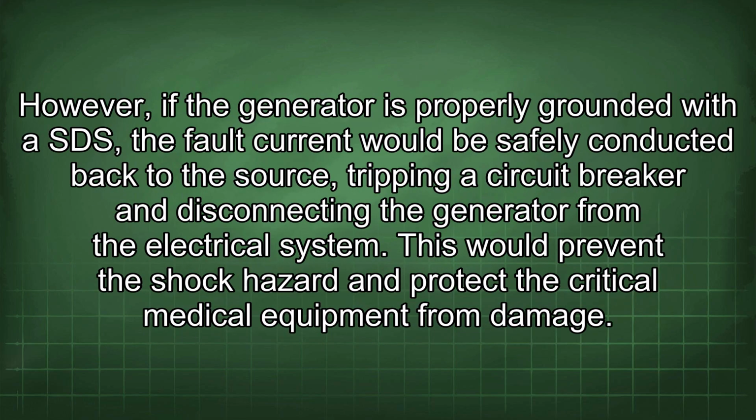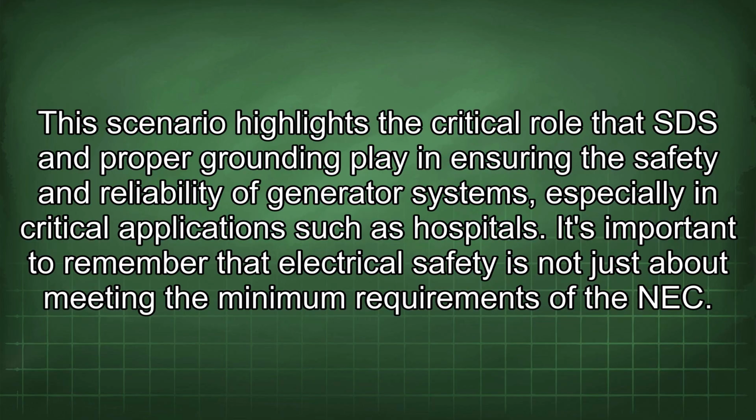In addition, the fault current could interfere with the operation of the critical medical equipment, potentially endangering the lives of patients. However, if the generator is properly grounded with SDS, the fault current would be safely conducted back to the source, tripping a circuit breaker and disconnecting the generator from the electrical system. This would prevent the shock hazard and protect the critical medical equipment from damage. This scenario highlights the critical role that SDS and proper grounding play in ensuring the safety and reliability of generator systems, especially in critical applications such as hospitals.